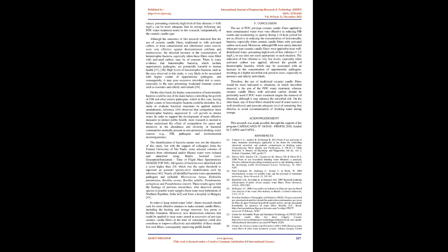Similarly, the type of ceramic candle filter, traditional or with activated carbon, did not influence the reduction of thermotolerant coliform and enterococcus significantly. However, a higher concentration of heterotrophic bacteria was observed in treated water using ceramic candle filters with activated carbon, TAC. The use of activated carbon to treat water has indeed been observed to facilitate and support the growth of bacteria 21, 22. Furthermore, it is also interesting to note that the concentration of heterotrophic bacteria in water produced by ceramic candle filters with activated carbon increased with time of use, reaching a roughly constant level after 5 to 7 weeks, which was maintained during the final weeks of the study.